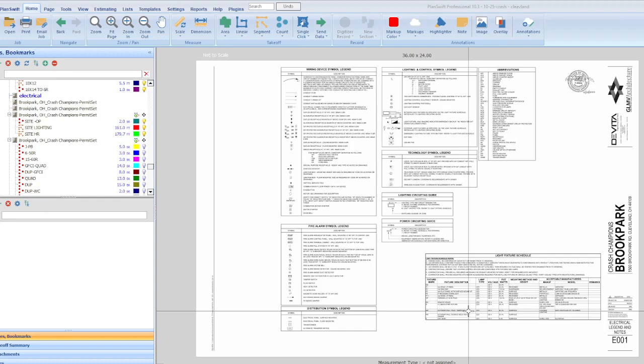But in a lot of cases they're not shown, especially for the lighting plan, so you have to understand the symbols on the lighting plan, and that can assist you in determining a route to draw your lines for your wire and your conduit.